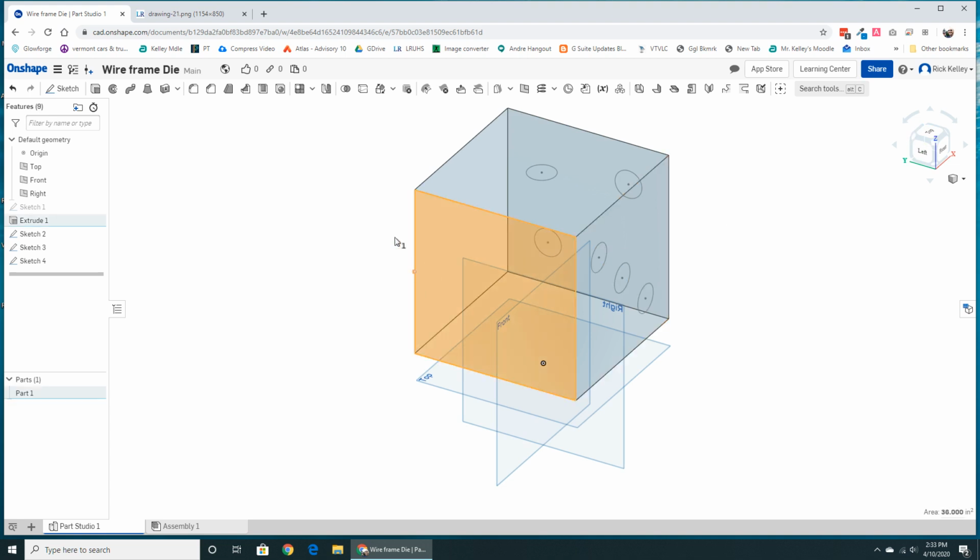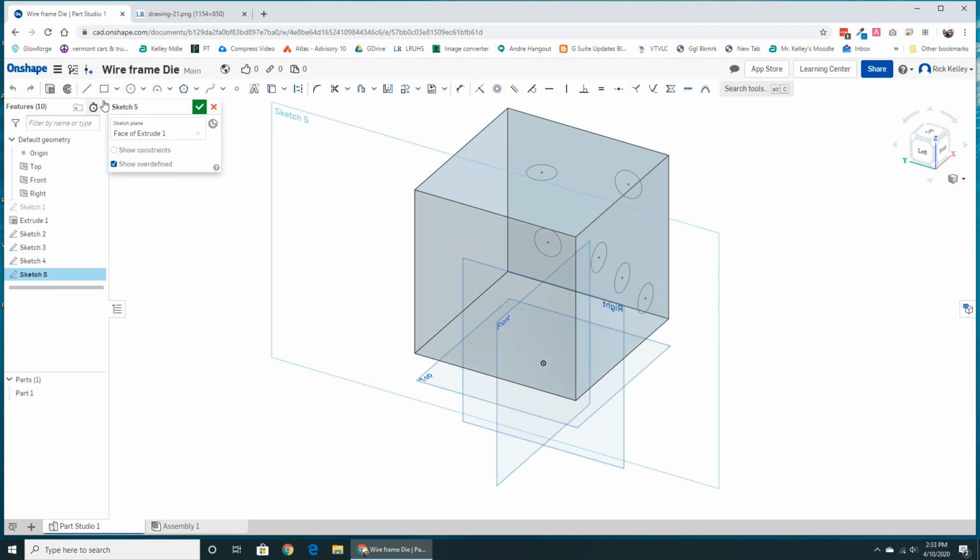All right, new sketch. And I'm going to do this one a little differently. I'm going to draw a circle. It's going to have a diameter of 1. Then I'm going to switch to construction lines and draw a line. I'm going to hover over this line until I get, I'm looking for midpoint. Where's that little snap? Right there. That little symbol means snap. Dot in the middle of the line. I'm going to click and look for the midpoint on the other side.